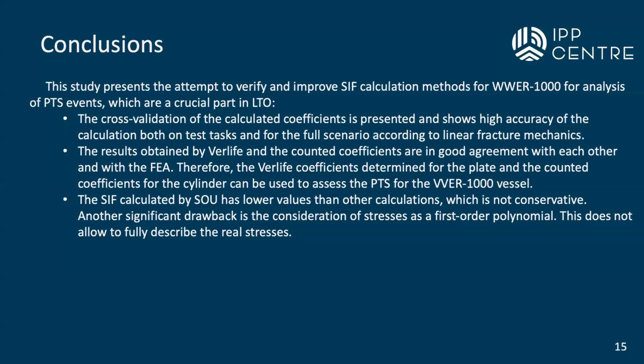The main conclusion is that the Vitalii coefficients, determined for the plate, and my calculated coefficients for the cylinder can be used to assess pressurized thermal shock for a VVER-1000 vessel.